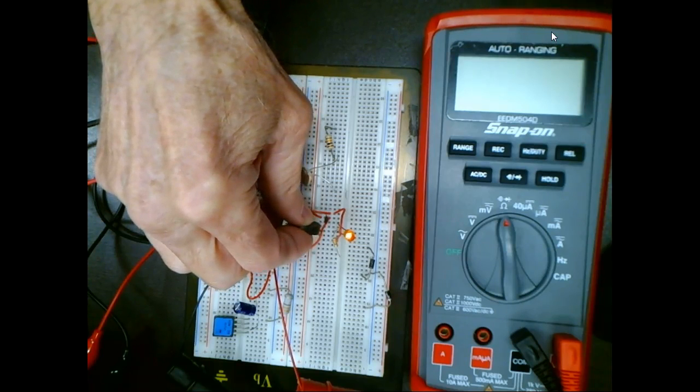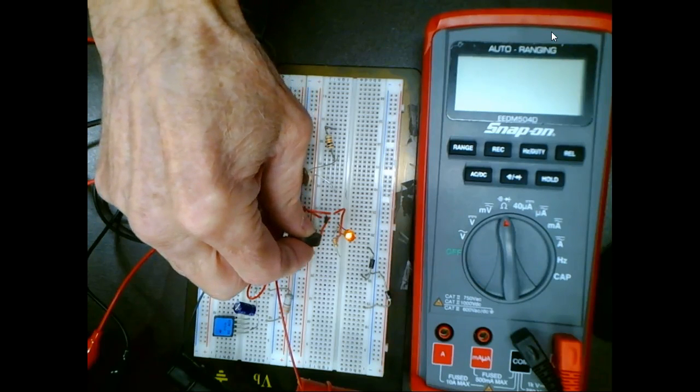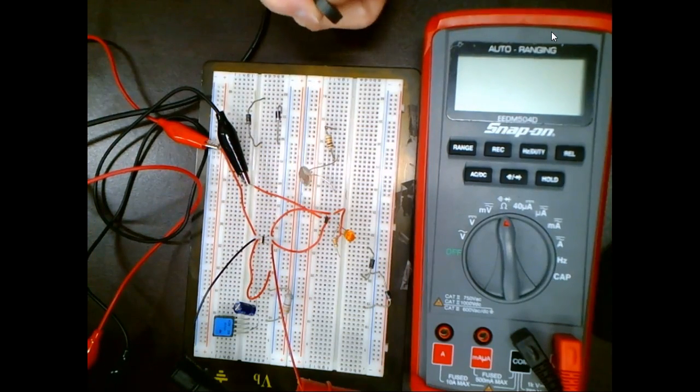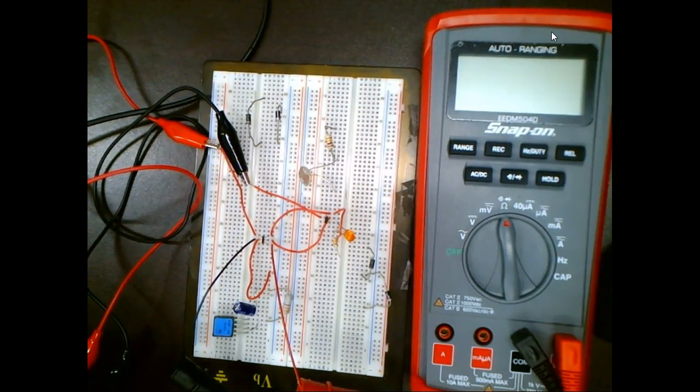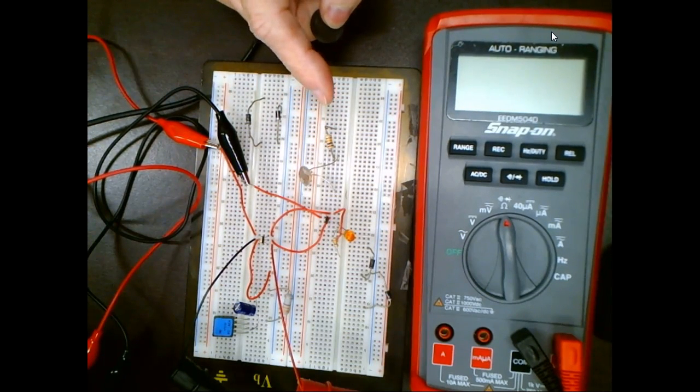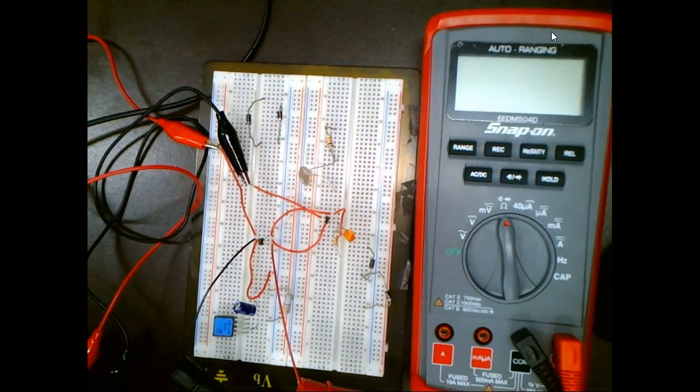And that's basically what it's using over there. This is analog. So this would be considered digital, right? You understand? It either turns on or off. But you saw how complex it was, because the Hall effect sensor itself is an analog sensor. So inside that thing, we have an analog to digital converter, a single bit analog to digital converter.